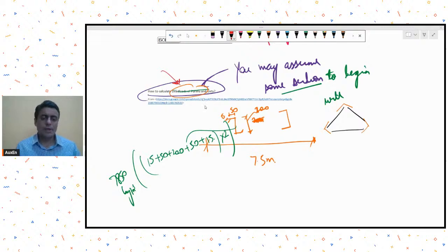In this manner, you can add up all the weights, calculate it in per meter units, and then apply it on purlins or girts, or on the rafter also after proper calculation. I'm not sure if this was what you were asking, but if you are asking about the dead load, this is how you need to do it.